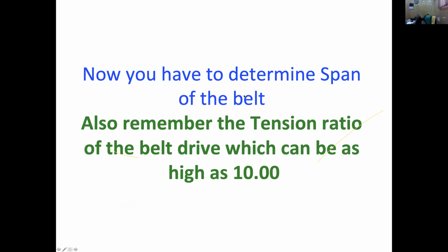The relationship is given in the books, and you can see that relationship. It is between the centrifugal force, the tight side tension of the belt, the slack side tensile force of the belt, the coefficient of friction, groove angle, and wrap angle. So you can see that equation. You can easily find what will be the T1 and T2 ratio. Please do that exercise also.